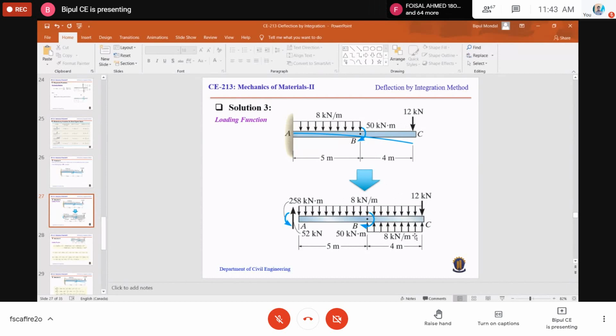So if we apply this amount of distributed load again within this zone, the effect of the two distributed loads will balance each other, because one is downward and the other is upward. So these forces will not produce any additional response in the structure. So this diagram and that diagram are equivalent.